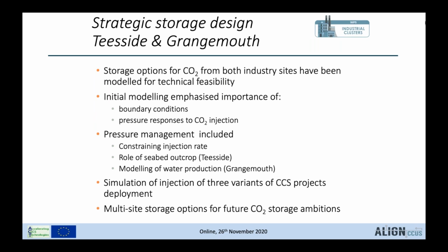So, taking a strategic approach to storage design, storage options for CO2 from both the industry sites have been modelled for technical feasibility. In the initialisation of our models and the simulation of CO2 injection, it has emphasised the importance of understanding the model boundary conditions and the pressure responses to CO2 injection. Our model pressure management activities have included constraining the injection rate, considering the role of a seabed outcrop at Teesside, and also modelling of water production at Grangemouth.